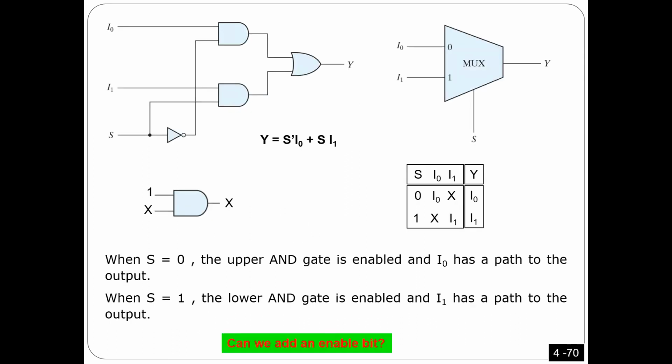Okay, how can you design this one? The way I'm going to do it, as you see here, is that I'm going to have two ANDs all the time. Now I have 2 cases, right? You have 2 inputs, 2 cases. So for every case, I'm going to have one AND, and then I'm going to connect everything together using an OR. I will always do it this way. Since this is a very small one, 2 to 1, as you will see right now, I'm going to give you 4 to 1 and 8 to 1. Okay. So anyway, in this case, look how it works.